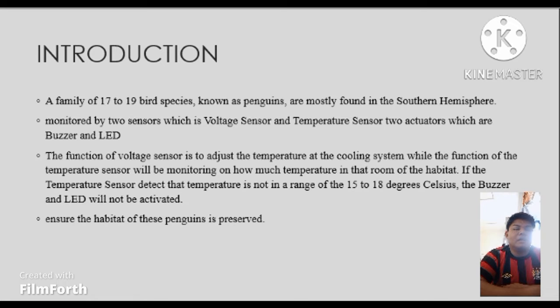If the sensors detect that the temperature is not in the range of 15 to 18 degrees Celsius, the buzzer and LED will be activated. By this project, it can be ensured that the habitat of this penguin is preserved. Zoo Negara can monitor room temperature accurately. The habitat can live more comfortably and give birth to more penguins, maintaining its environment.